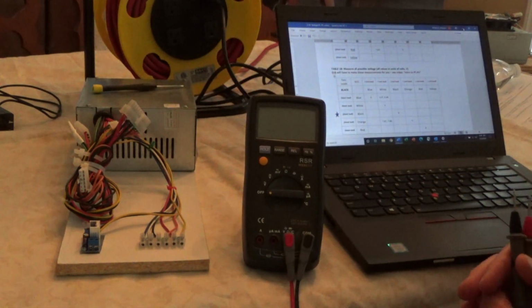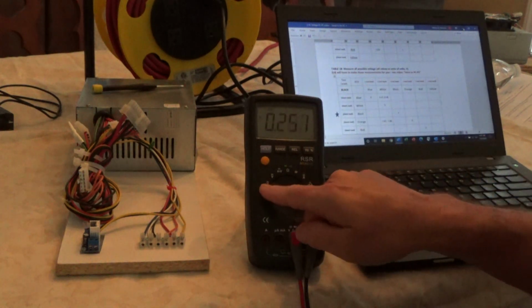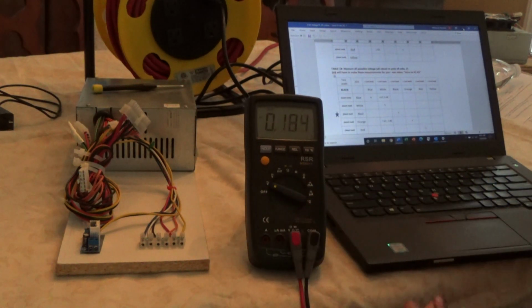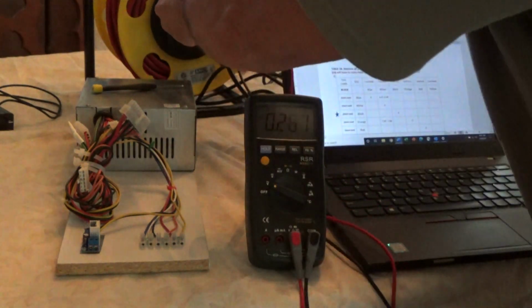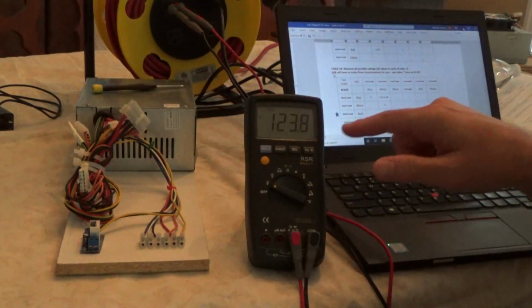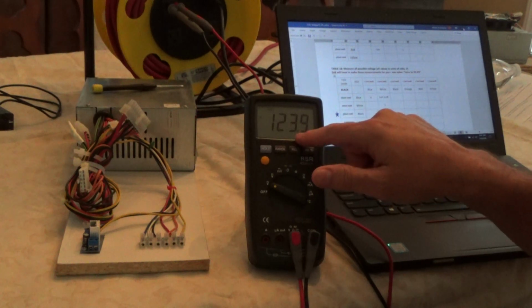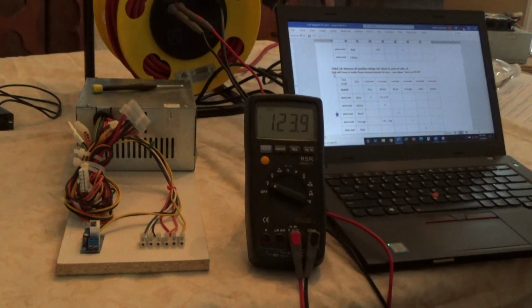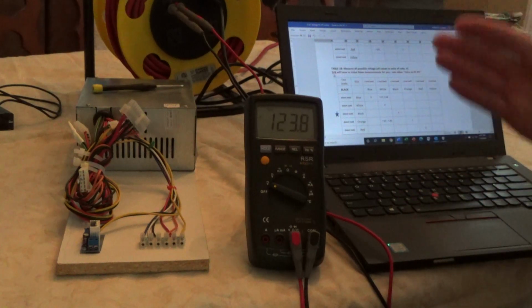Now, the first thing you might want to notice is that I'm going to turn my meter to measure AC voltages. And notice that we have to plug this into a receptacle, and if we measure that, you might want to just know that your AC voltages in your home, this is called US mains. Around here, we see it's about 125 volts or so AC. So that's an AC voltage. It's a voltage that changes polarity 60 times a second. The frequency is 60 hertz.